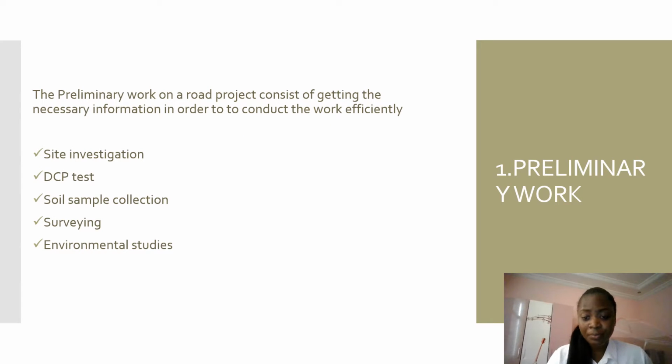What is the preliminary work? The preliminary work on the road project consists of getting the necessary information in order to conduct the work efficiently. So there we see the site investigation, the DCP test, the soil sample collection, the surveying, and also the environmental studies, because if we want to upgrade, if we want to improve, we need to have the existing situation so that we can efficiently do the design. We can efficiently propose